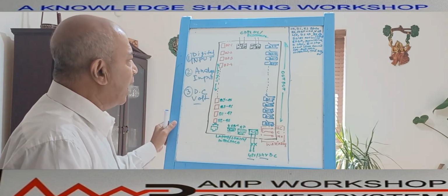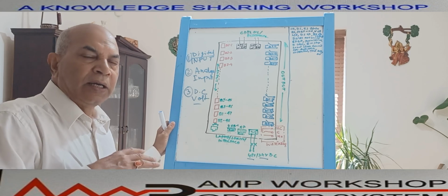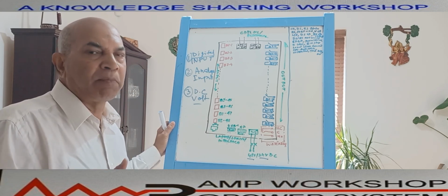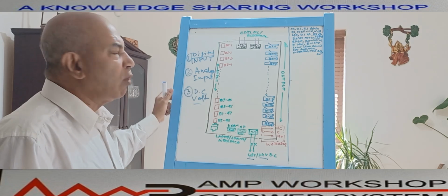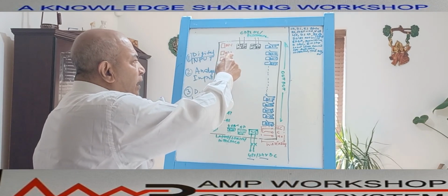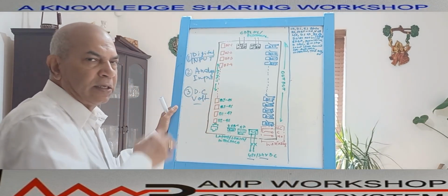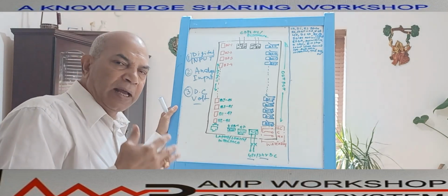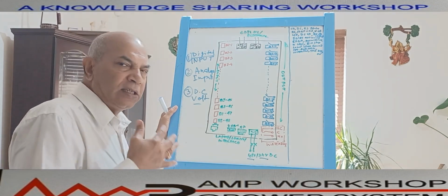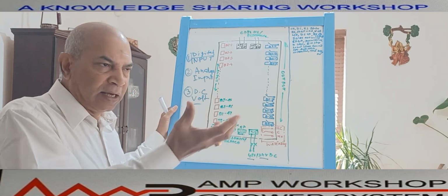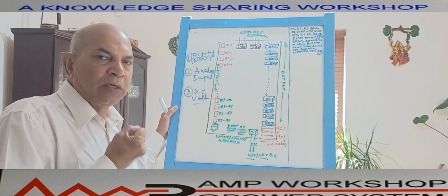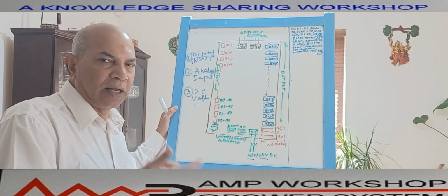Then the digital relay, as it can take the potential free contact, it can also give output as a potential free contact. That is what we call digital output or binary output. The digital input we call binary input. Those binary inputs, how do we identify? Binary input 1, binary input 2, binary input 3, depending on how many there can be. Similarly, this relay can give output as a digital output. The digital output is a potential free contact, as it can receive the input as a digital contact or binary input. Similarly, it can give the potential free contact that we have discussed.